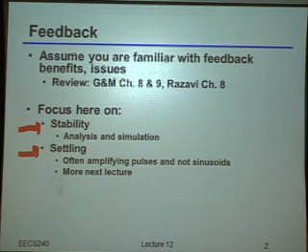And I say that only for the following reason. It turns out that different methods get you to the answer most quickly in different situations. In some situations, it's really easy to just look at a circuit and say, look, this is the equivalent block diagram, I immediately know what the answer is. In other situations, it's easier to inject a voltage source or current source somewhere, track it through the loop, and measure the response. As you may have been hinting at, there are certain situations, particularly in simulation, where it's pretty hard to break the feedback loop correctly, and there are some other tricks you have to play. Again, I'll talk some more about that as we go through the lecture.